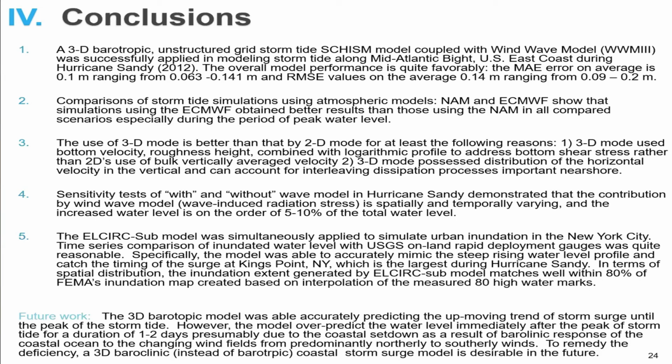First, we showed a time series comparison with the USGS on-land deployment gauge, and it's quite reasonable. Specifically, the model was able to accurately mimic the steep rising water level profile and catch the timing of the surge at Kings Point, New York, which is the largest during Hurricane Sandy. In terms of spatial distribution, the inundation extent generated by LSEG matched about 80% of FEMA's inundation map, which is created based on interpolation of the measured high water marks.